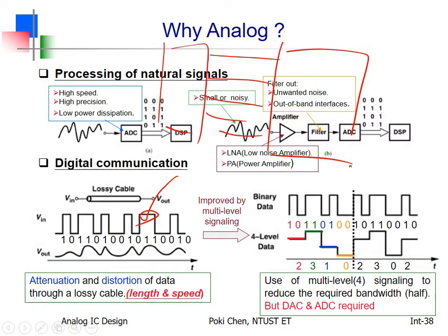You have a lot of data, a lot of I/O control bits, anything, okay? In the past, everything is synchronized by your clock, by your reference clock, all right? So maybe right now we have 64 bits or even 128 bits for such kind of parallel communication. I don't care. For 64, so you have D0 all the way to D63, right? So what is the problem for clock skew?